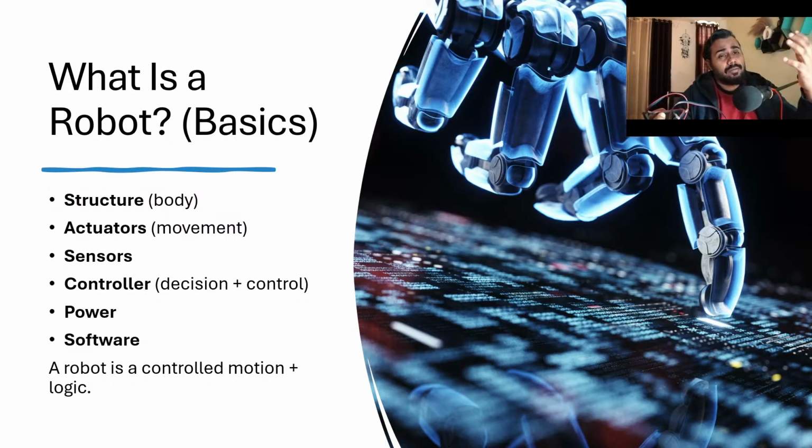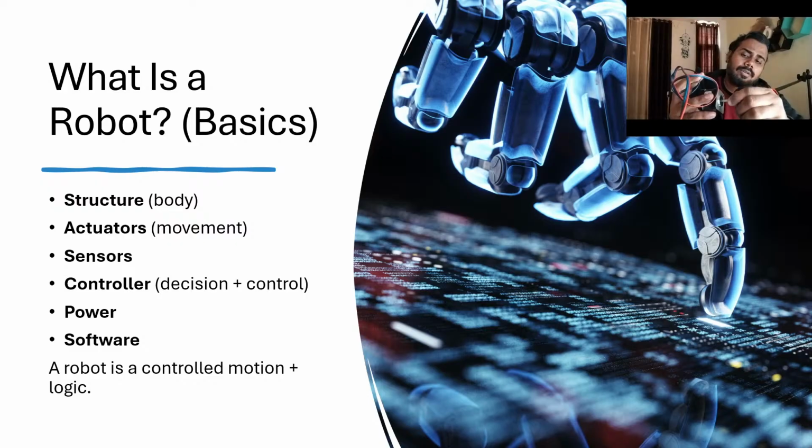So you may have seen robots moving in a certain direction slowly. This one motor can give you at least 200 iterations of motion. One coil pulse can move this by 1.8 degrees. It depends, there are other variants as well, obviously. And this motor is capable of lifting a certain amount of weight. This one has a capacity of maximum 5 kg.